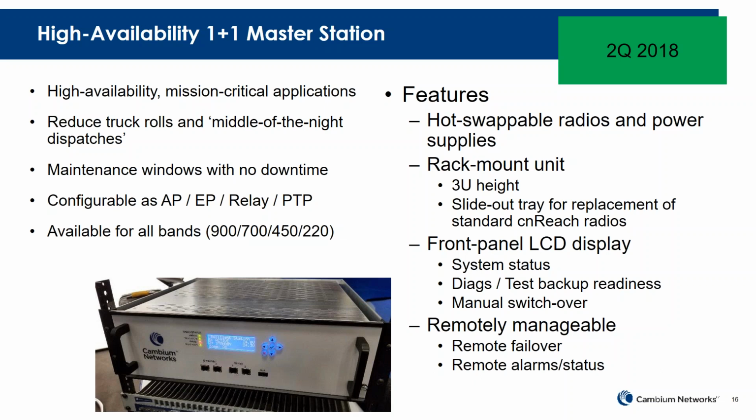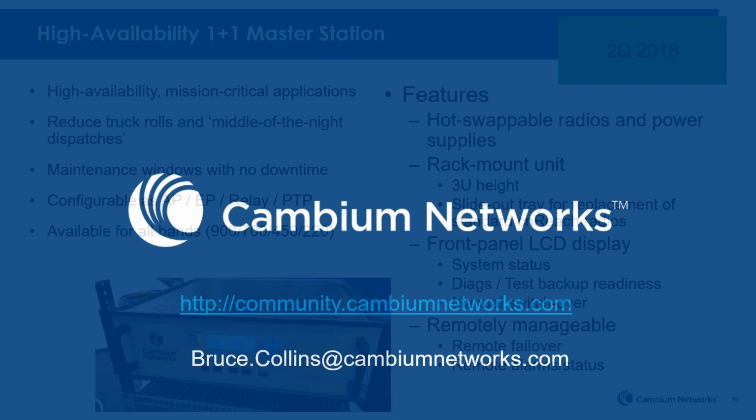The other thing is the radio also monitors the communication. So it's not just power loss or the radio not being responsive. It's actually looking to see if historically I've had, say, 10 radios in my neighbor list, talking to 10 different radios as an access point. If all of a sudden I'm not talking to any radios, then the assumption is that something has gone wrong. So it's a functional test as well as a physical test that the radio is operating correctly. You get some nice analytics that go into that as well.